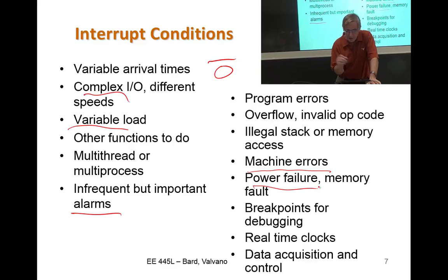Power failure is a fun one. We'll get an interrupt when the power's going down. Some debuggers, not this one because it's JTAG, use interrupts for breakpoints or for single stepping, and we're going to use them for clocks and both the A to D and D to A.